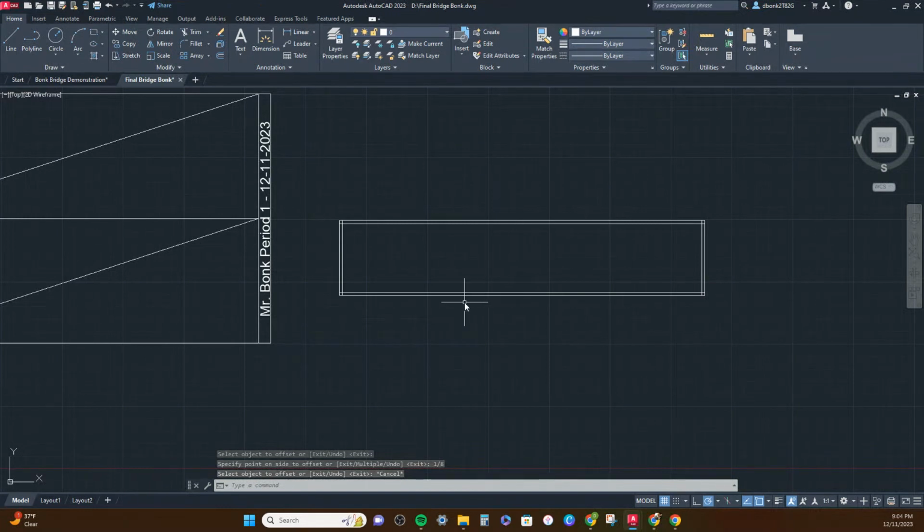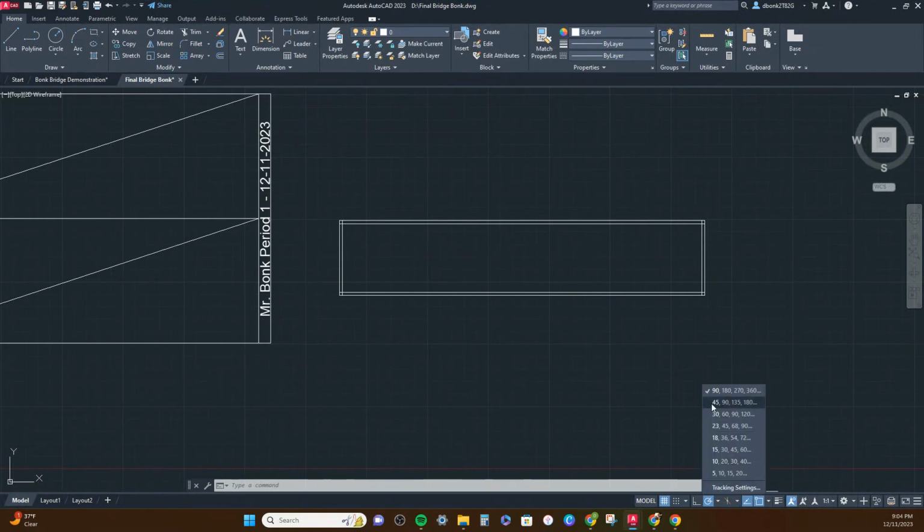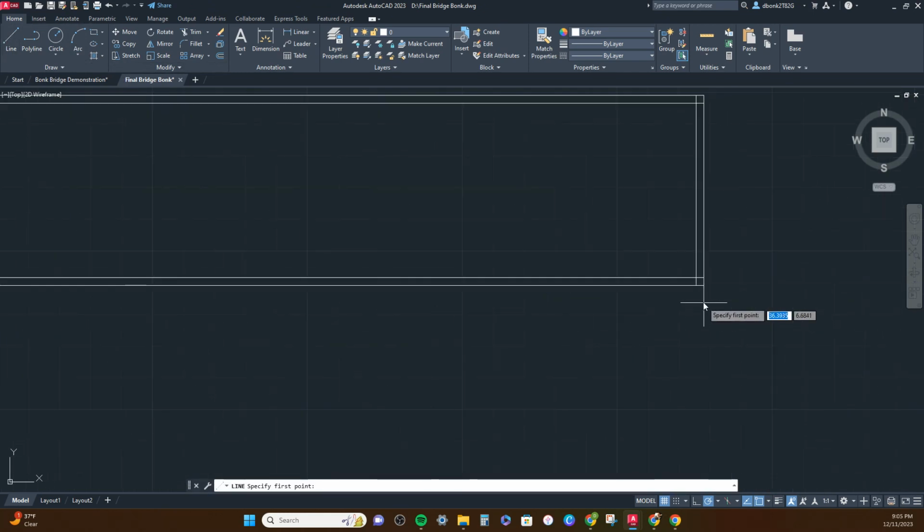That's just going to be a quick rough outline for the bottom deck of the bridge and the top chord, what it's called. You've got to make sure now, in this case here, angular snaps are set right. You want this set up where this is going to snap at 45 degrees when you start drawing a line at 45 degrees. So you could take this line tool now and go from the bottom corners up at 45 degrees and just finish it off.